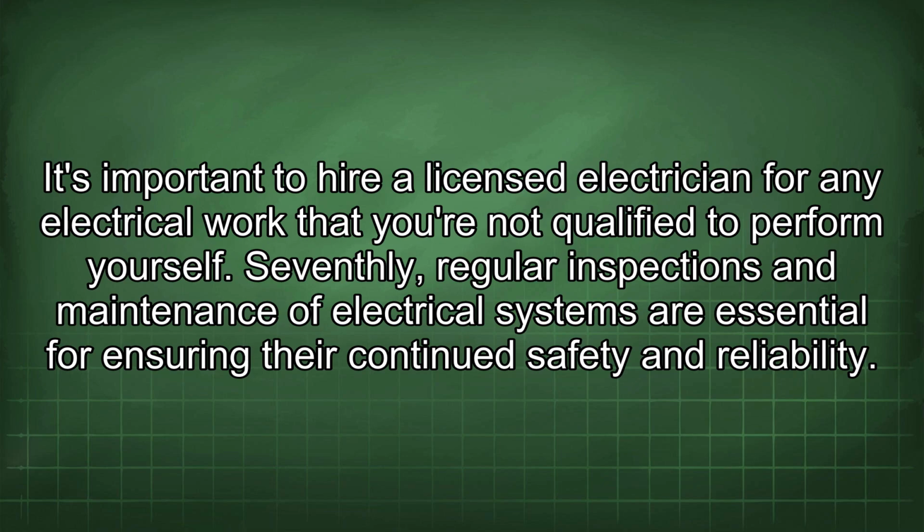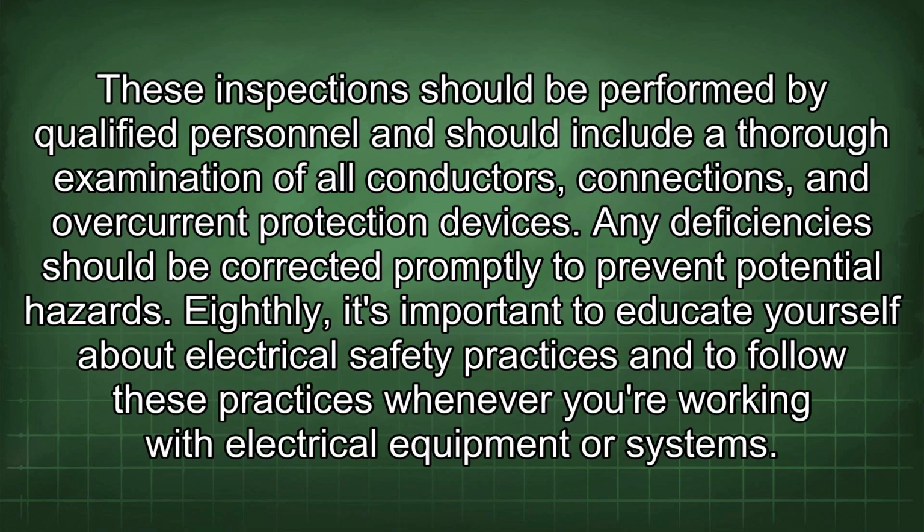Seventhly, regular inspections and maintenance of electrical systems are essential for ensuring their continued safety and reliability. These inspections should be performed by qualified personnel and should include a thorough examination of all conductors, connections, and overcurrent protection devices. Any deficiencies should be corrected promptly to prevent potential hazards.